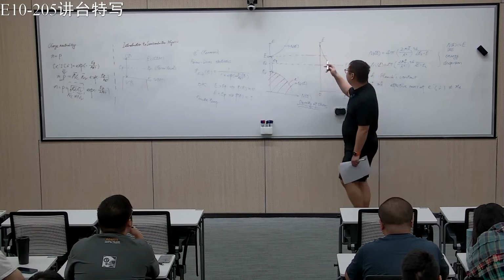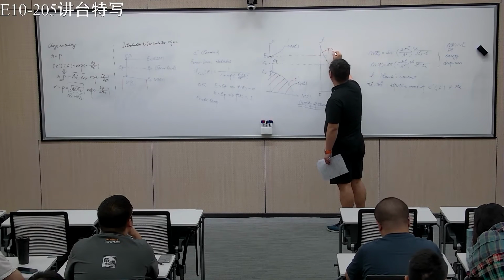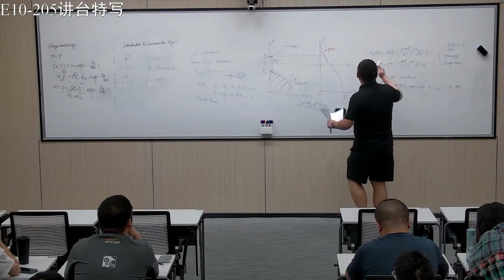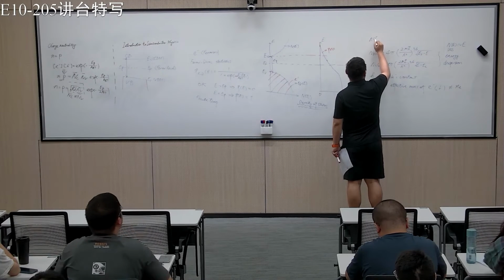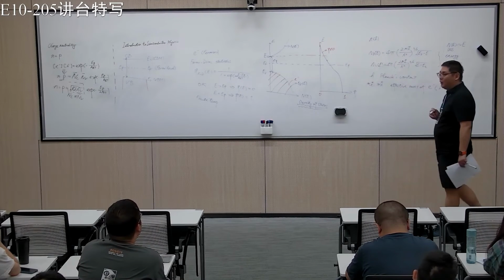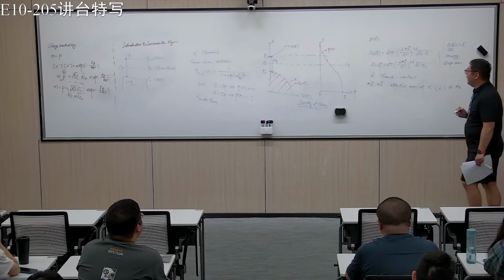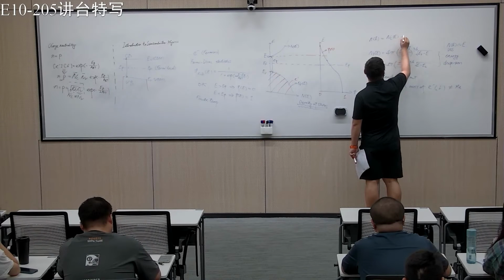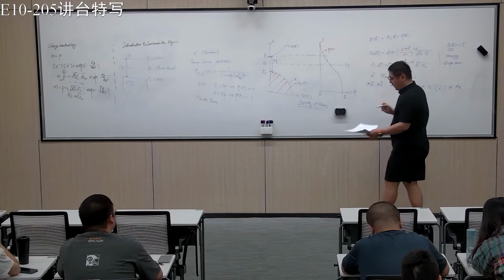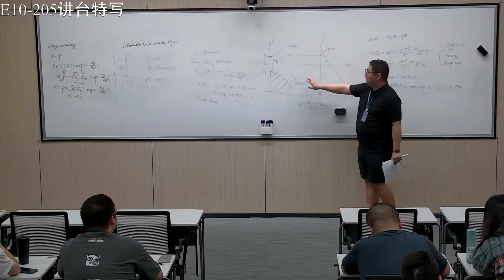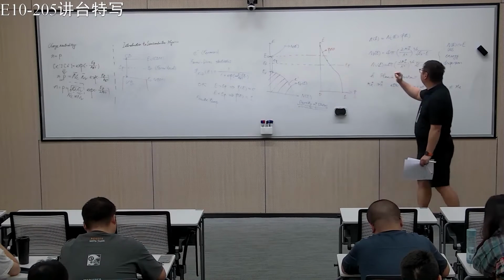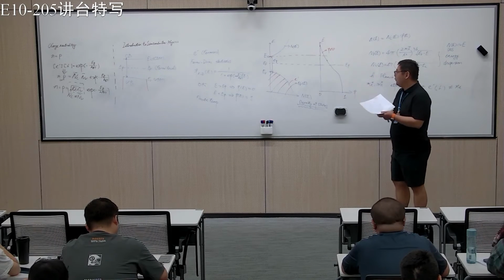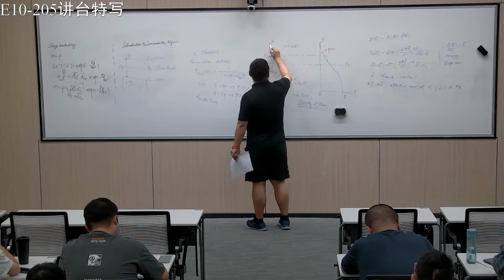Because this F is not zero. So we can define the number of electrons, the local number of electrons as a function of the energy, is NC times Fe. So basically we multiply this function, which is described here, with this function. The end result is you have something that looks like this.